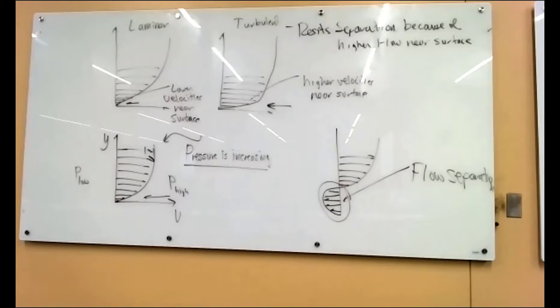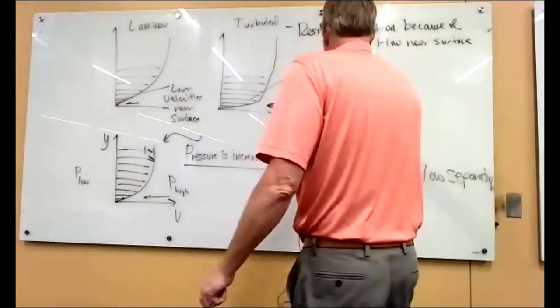You build a turbulent flow airfoil, and it's got a lot of drag when you're trying to cruise, but when you come in for landing and you need a lot of lift, it's going to resist stall, so it's going to be stall resistant. So what you do as a designer is you pick the best of both worlds. Makes sense, right? That's what we all want to do.